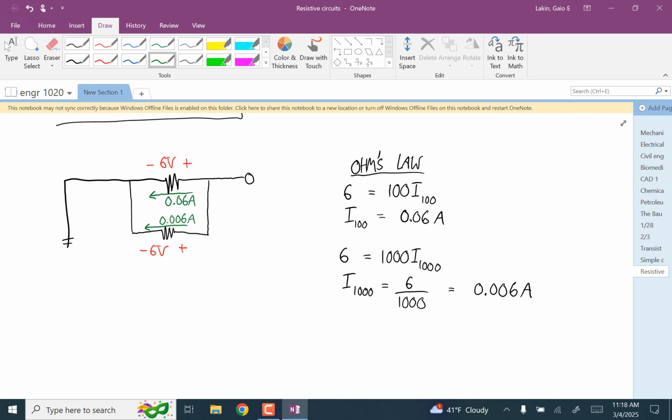So if this had zero resistance, all the electricity would just flow with no difficulty at all through here. None would go through here. If you have sensitive circuits, some kind of microprocessor or something, you'd get a very high current because you have basically zero resistance, and the effect would be to break something in your circuit.